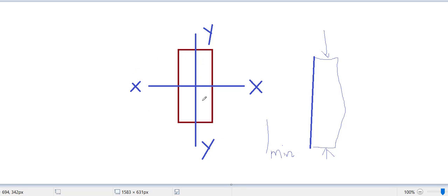So here, if you consider this axis, your moment of inertia is b h cubed by 12. If you consider the other axis, it is again b h cubed by 12. Now the cube power, if I consider this part, it is huge. So I about this axis is huge, but I about the y axis is less. So my I_y is minimum here.